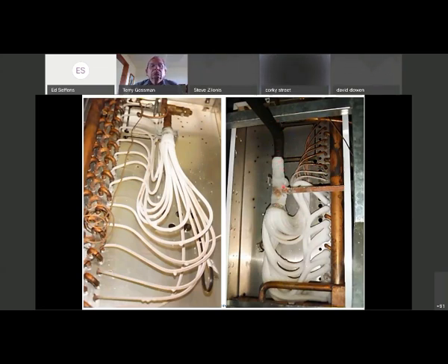I personally like to see the expansion valve close coupled to the distributor if at all possible. Here we have the expansion valves somewhere over here, and then you have a U-bend, a 90-degree elbow here feeding the distributor. So portions of the distributor tubes are being fed, and then half of the distributor tubes look like they're not being fed. So you have unequal distribution through the evaporator, and that could be a huge problem for efficiencies and stuff.